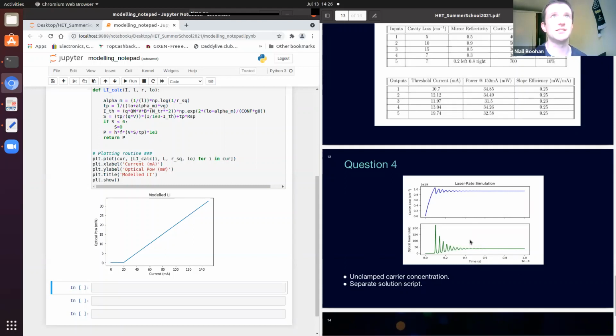The reason I didn't do this is, this is another relevant example, this calculation takes quite a long time to do on your computer. It'll take maybe 5-10 minutes or something like that. So it wouldn't be reasonable to do it during a presentation like this. So that was one of the reasons why I went to a steady state. You have to keep in mind your available computing power when you come up with these models, and particularly how much resolution you go into in the calculation.